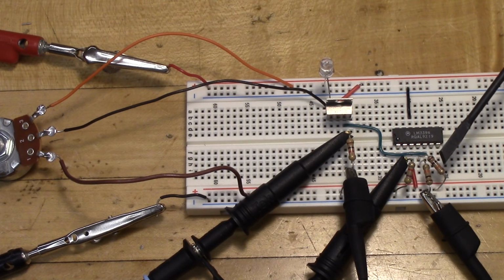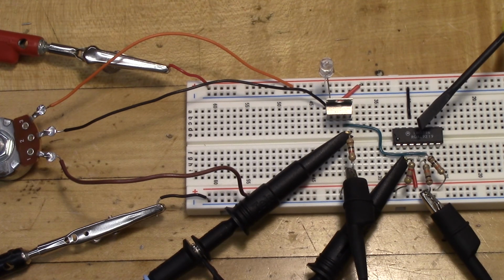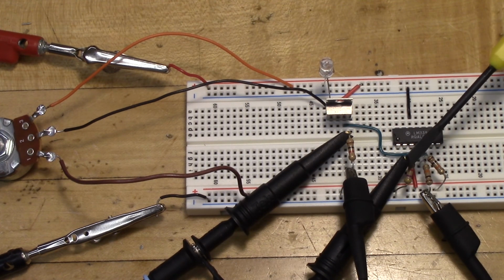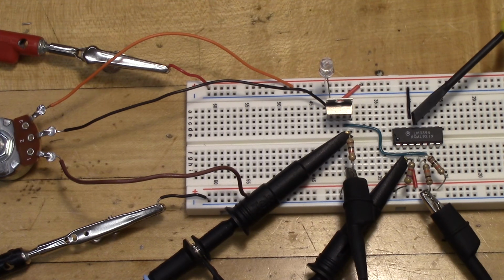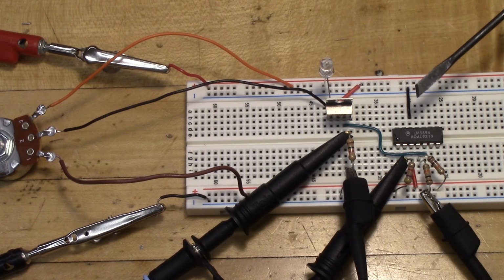I've got my 10K pair of voltage divider connected to pin 4, the inverting input, and my 4.7K pull-up resistor on the output. I'm using the LM339 quad comparator. Ideally, I should have all these other unused pins tied to ground, but I'm not doing anything so sensitive that it's really going to throw it off. There might be some internal noise if you're doing something else.